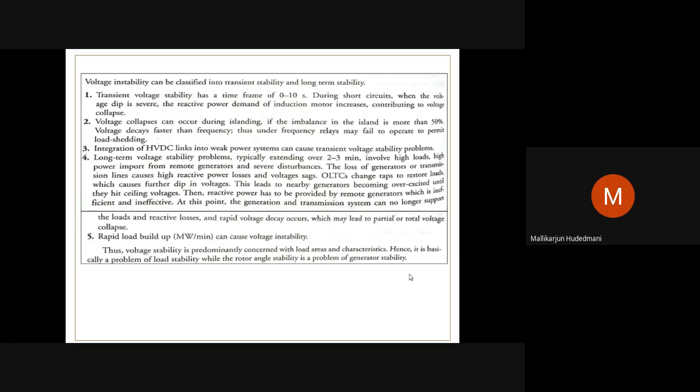So that weak power system, having an interface with the HVDC link, a high voltage DC link, gets extended, or from the HVDC it is getting a response input. So there must be transient voltage stability problems. The system is already weak, and any such subsequent changes won't be reflected in time. Definitely the system will suffer from this. That would be one reason.